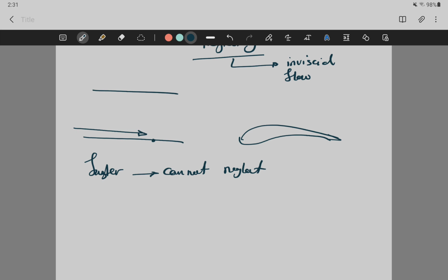Can we neglect it and just have that be part of our efficiency? That's what we are going to do eventually, yeah. But in reality, can we neglect this? Isn't it just relative though? Because we're only looking at our inputs and outputs. Eventually we are only going to look at this as the efficiency part, right? All of the losses are going to be combined inside the efficiency, but the flow itself cannot be assumed to be inviscid, mainly because of what you guys mentioned, and there's a flow inside a small duct, right?